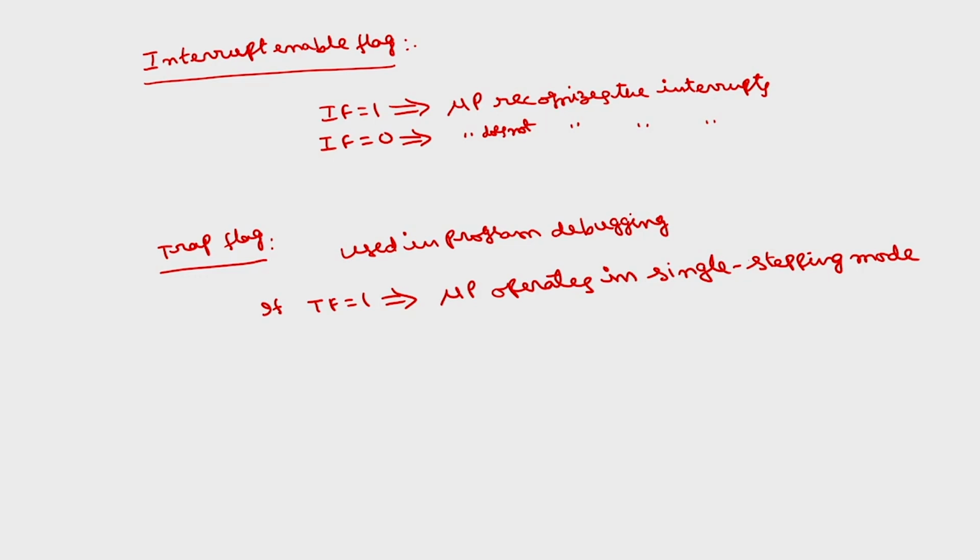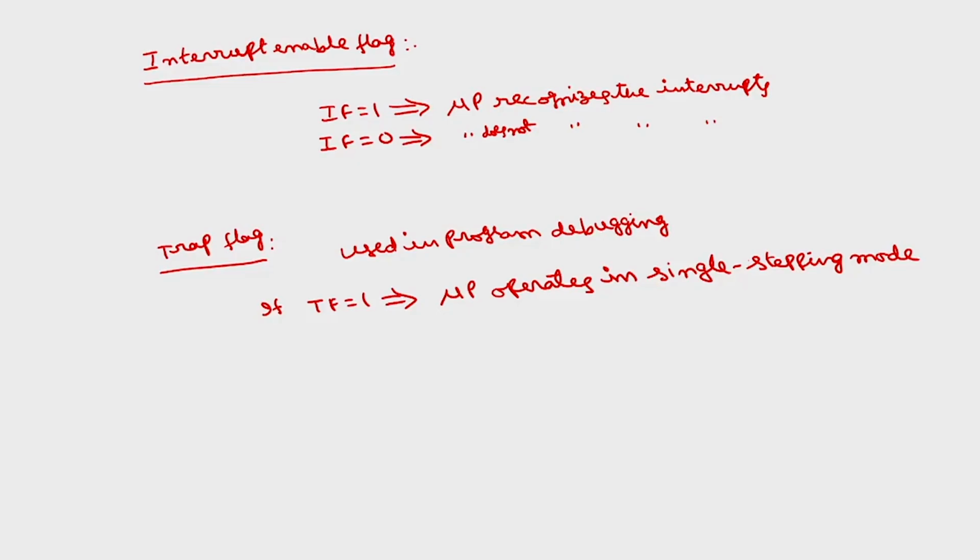At the interrupt service subroutine, you can write a program to display the contents of the registers and memory locations. So, for example, if you have instructions like MOV AL, BL, INC CL, LEA with some address like 6000H, some sort of instructions, I will describe the instructions later.